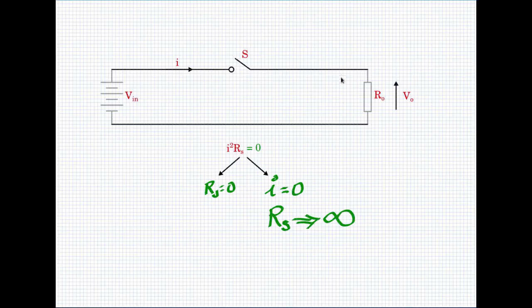However, the voltage V0 is no longer continuous pure DC. It is pulsating. When the switch S is on, then you have a DC voltage of Vin appearing here. When the switch is open, the voltage across V0 is 0. So it goes high, low, a pulsating voltage. It is called a chopped voltage, and this circuit becomes a chopper.